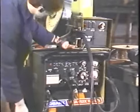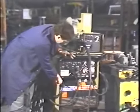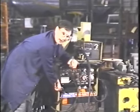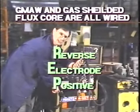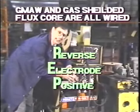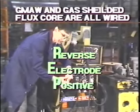The easy way is simply to check that the ground cable is attached to the negative side. I've always remembered it the old simple method: reverse electrode positive stands for the Republican Party, REP, reverse electrode positive.